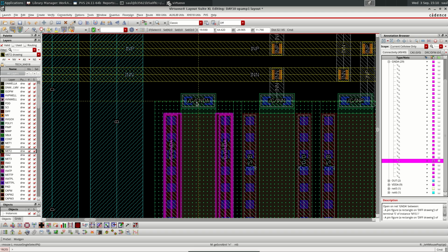So what we can do is we go to metal 1, and then we select P for path, and then we can take it from any of the gates, and then we go down. We don't even need to click immediately. It finds its way to the source or drain. So click it and it is connected. So we have 29 and we have 28. We do the same to the other side.